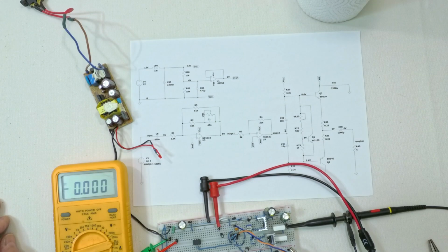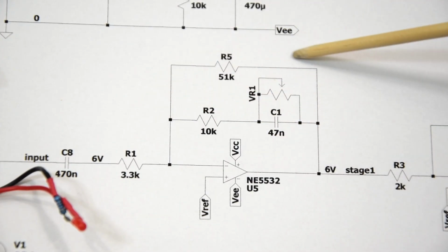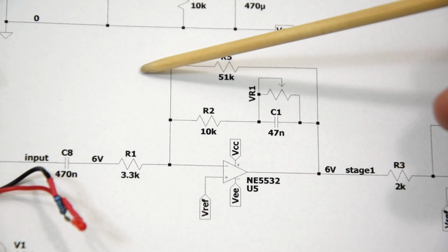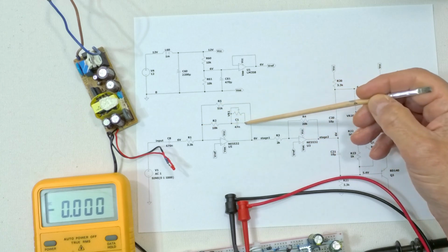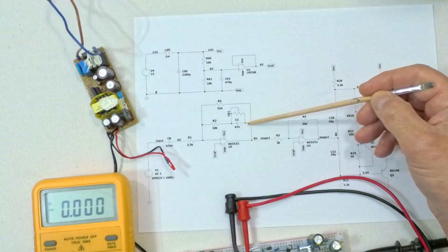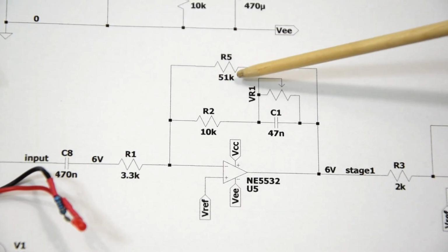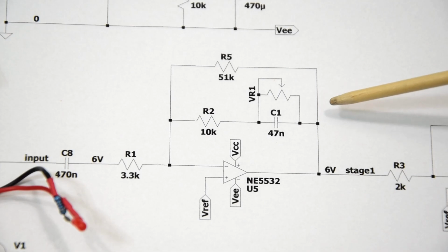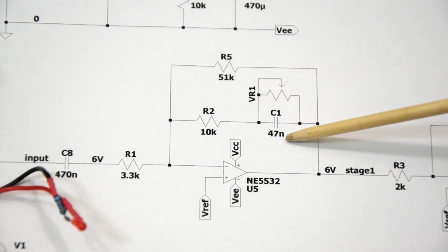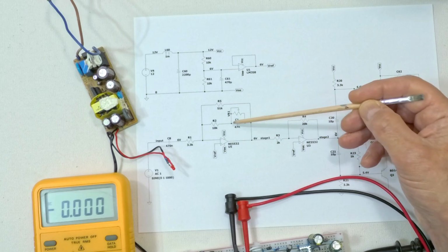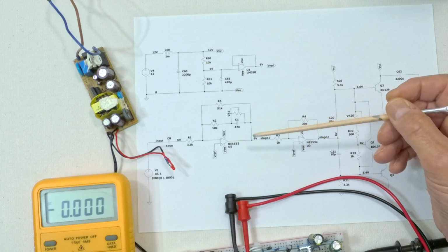So I updated the schematic once again. I put in this tone control circuit in the first stage of the amplifier. As you can see, the path for the high frequency signals and the path with a higher gain for the low frequency signals. And of course the variable resistor over the capacitor to control the tone adjustment that's taking place in this circuit. So let's take a look at the breadboard and see how it turns out in real life.